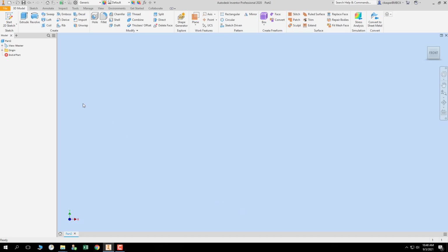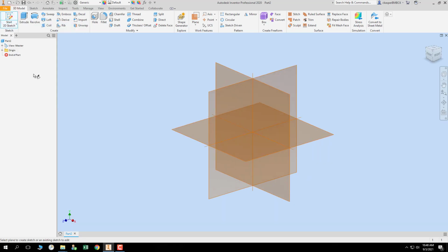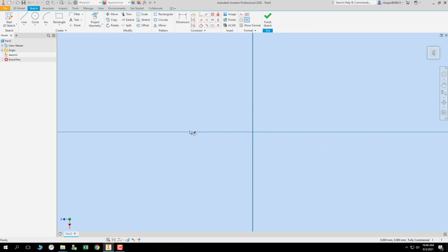I'm going to start with the line tool. Of course, every sketch starts with a 2D sketch. Every project. We will choose the XY plane, which represents the build plane, or the build plate of your 3D printer. And of course it rotates us so that we're looking straight down at it. Now one thing I try to remember to do is, when I look at this orientation cube, top is sideways. I like to rotate it so that it is straight up and down. I clicked on that arrow to do it. So now I'm looking straight down at it from the front of the machine. And that's the way I want to orient it.